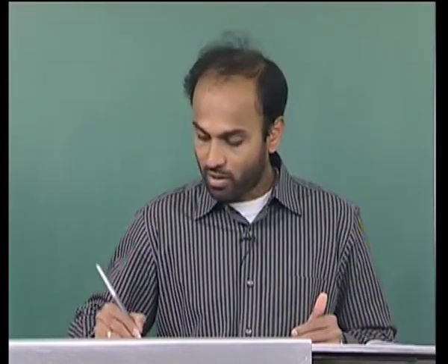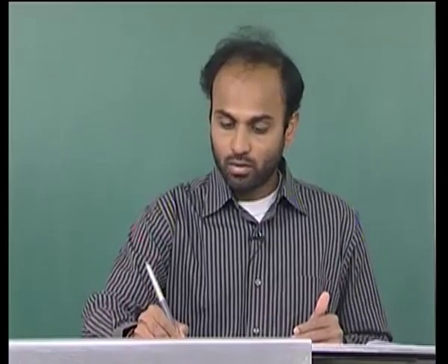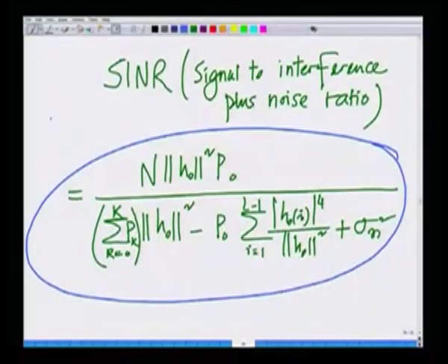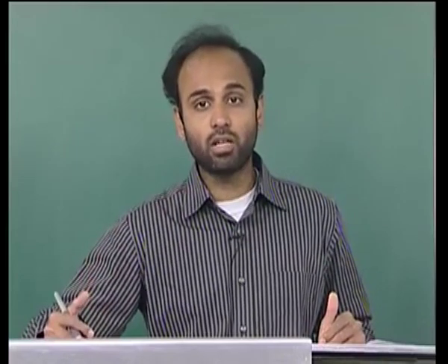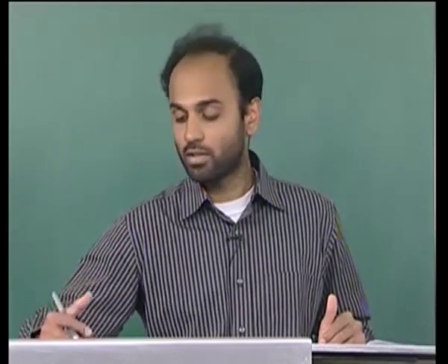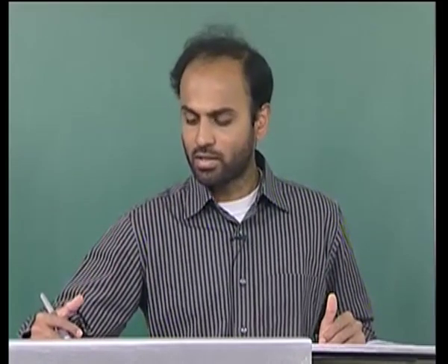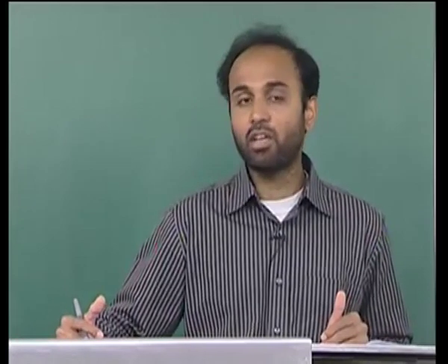And finally, what we have arrived at in this expression over here is the actual multi-user SINR of the desired user, taking into account, not neglecting anything. In fact, this is not an approximation, this is an exact expression where we have considered the multi-path interference, the multi-user interference and the thermal noise at the receiver. So, this is a thorough expression and it is fairly strenuous, but remember, a couple of key observations.